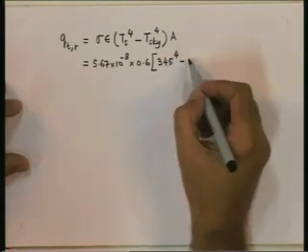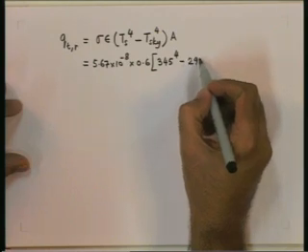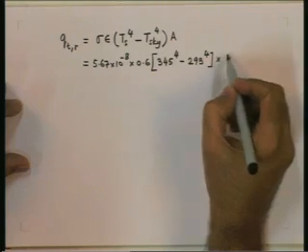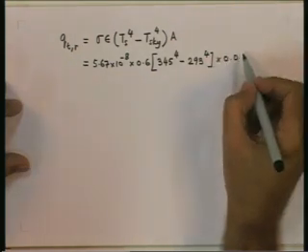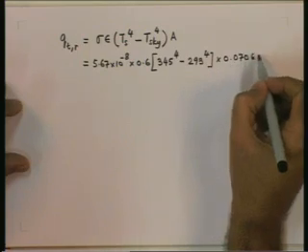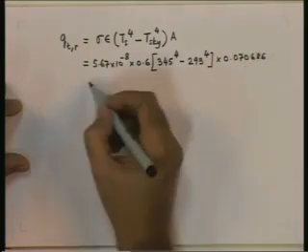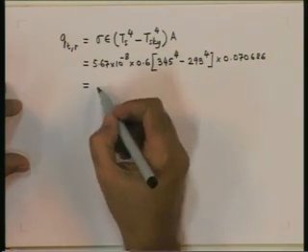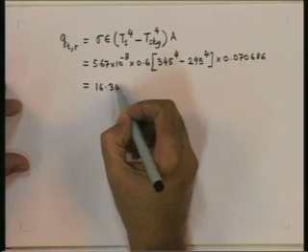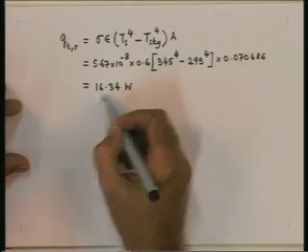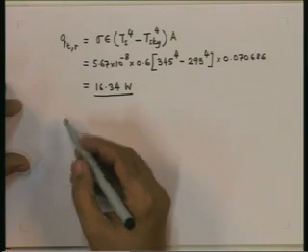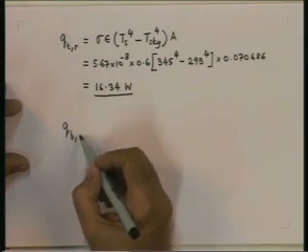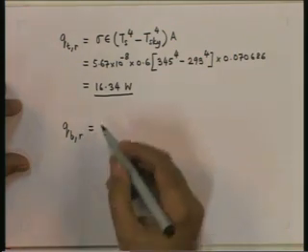Sky temperature is 20 degrees C, that will be 293 Kelvin raised to 4, multiplied by area 0.070686, and this turns out to be 16.34 watt, one component.